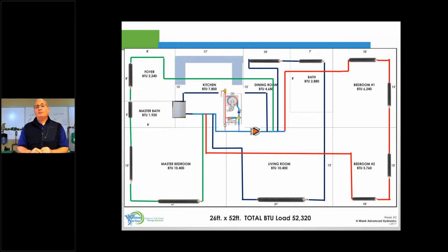By multiplying it by 1.5, what we're doing is we're actually adding 50%. I'm not measuring up every single piece of pipe, counting every elbow, any T, or any pressure drop going through any valves. By adding 50%, we're adding that in there. We're adding the fudge, as we say, into that. And then multiplying it by 0.04 means I'm not going to move the water through the piping any faster than 4 feet per second. So if we did that for 84 feet, take 84, multiply that by 1.5, multiply that number by 0.04, and you should get 5 feet.